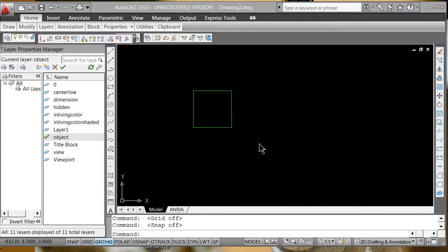Now I'm going to show you the key thing that you need to be doing when you are laying out schematics, and that is to make sure that your grid size and your snap size matches the set of blocks that you are using to do the schematic. You turn the grid and the snap on and off by holding a chord of the F7 and the F9. I'm going to push the two of them together now, and I just turned them on.